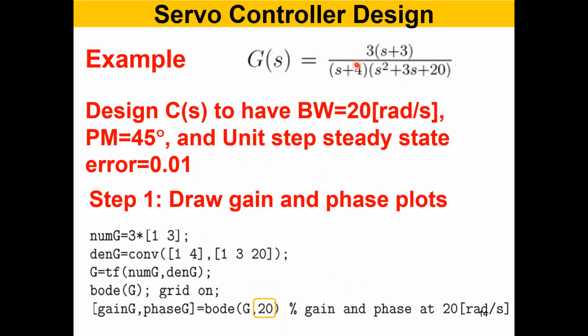So remember, for the transfer function, if you introduce any value for S, say pure frequency, it becomes a rational polynomial of S. So when you substitute S equals j omega, for example, it's a complex function. You can calculate the gain and phase. So that is the gain and phase of the block for that particular frequency. So you can manually do that.